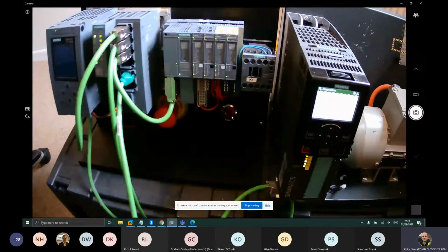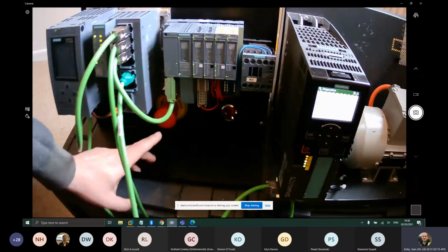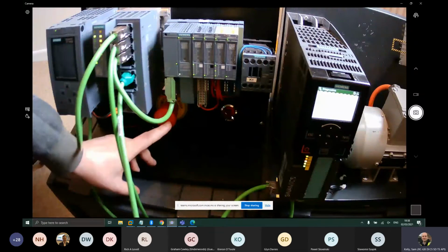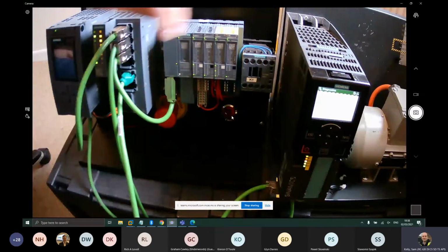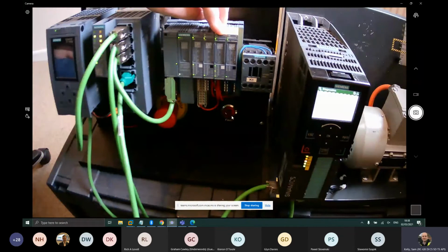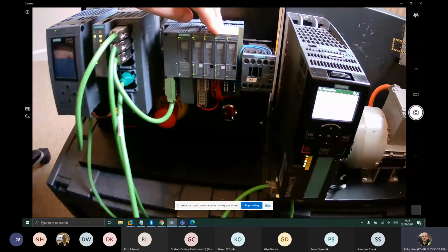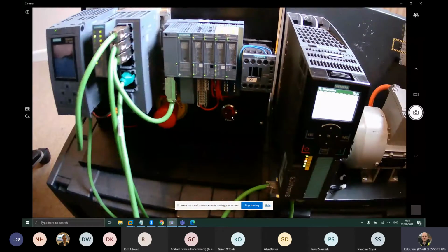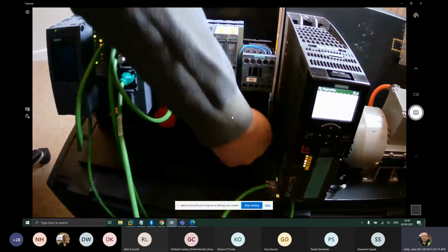What that's going to do is break one of the channels of this e-stop. So this e-stop is connected to our fail-safe digital input card with what we call 1 out of 2 evaluation. So if we break one of those inputs, we'll have a discrepancy fault, and of course we'll trip our IO. So let's go ahead and create that fault.